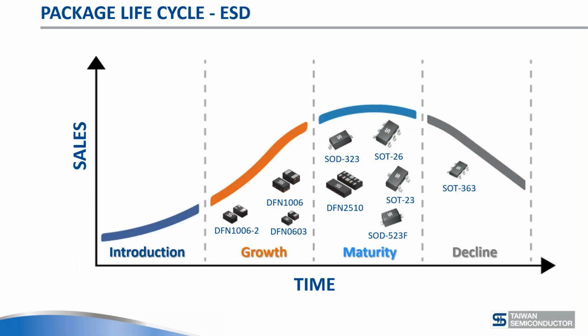For ESD, there are a few important, famous interfaces, USB, HDMI, that type of stuff, and a couple of other ones you want to protect against. The product proliferation comes historically from the package perspective. In the past we made SOT23s and SOT26s. We continue to offer those devices, but obviously these are the older parts. Most of our new parts are DFN packages.